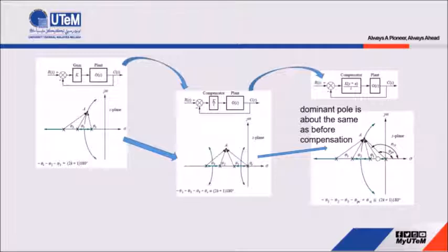To be more clear about this, let us look at this figure. This is the block diagram that represents the system that we have discussed. For the system with three poles, the number of branches is 3. So we have the direction for the root locus, the direction of the poles when K is increased, based on 3 roots. This is root number 1, this one is root number 2, and this one is root number 3.